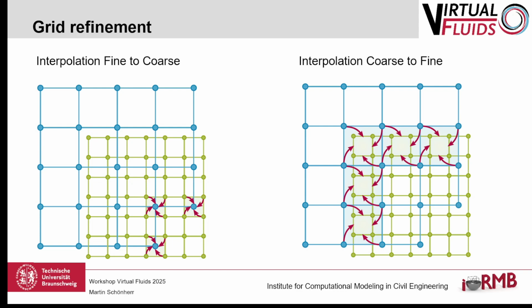So one line breaks down, the next line, and then we do the interpolation. You always have to be aware of this when you set up whatever you want to simulate. You always need this space for this interface, and we suggest having the same minimum amount of nodes in between two interfaces, right?